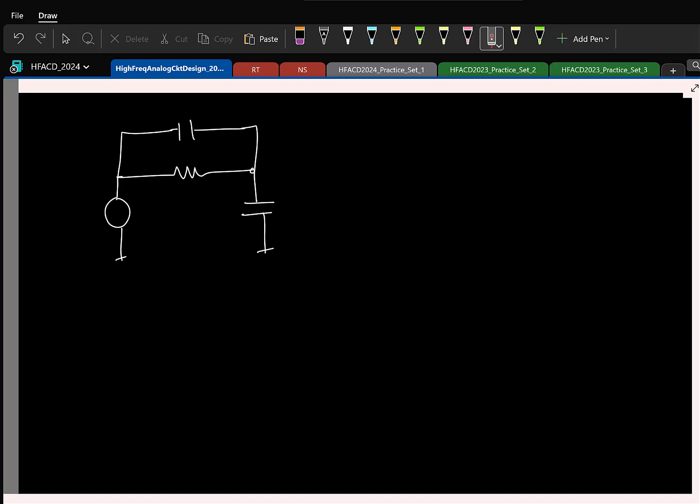Yeah, that is one thing. Impulse current is flowing, and even otherwise, this is basically acting like a short circuit or a very low impedance. So if I put these two in parallel, now we have two low impedances like this. So it will be a division between those two impedances, right? You can think of it like this. It has some Z1, Z2, where both of these two tend to 0. But one of them will tend faster to 0 than the other, because capacitor impedance is 1 by SC1, 1 by SC2. Depending on which is offering a lower short circuit than the other, you will have a division. That's all.